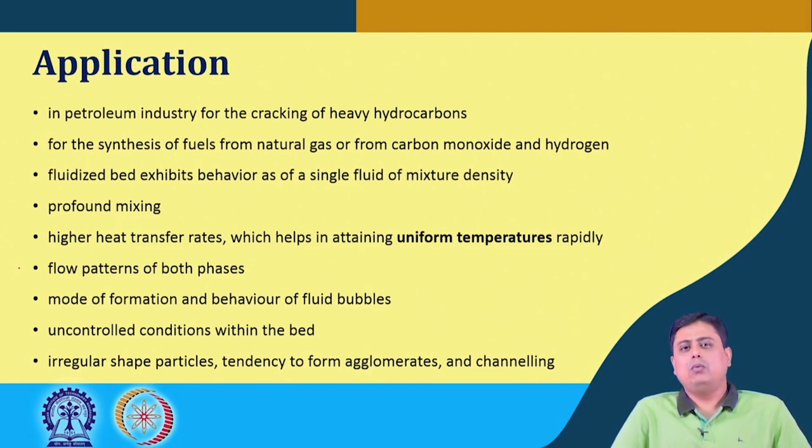When this fluidized bed is used, it basically exhibits a behavior as if there is a single-phase flow that has a density equal to the mixture density. There are solid and liquid, or let's say solid and gas phases, both with their own density. Now you can find out the mixture density. The model was typically developed earlier for the fluidized bed considering that it has this mixture density and behaves as if it were a single-phase system.